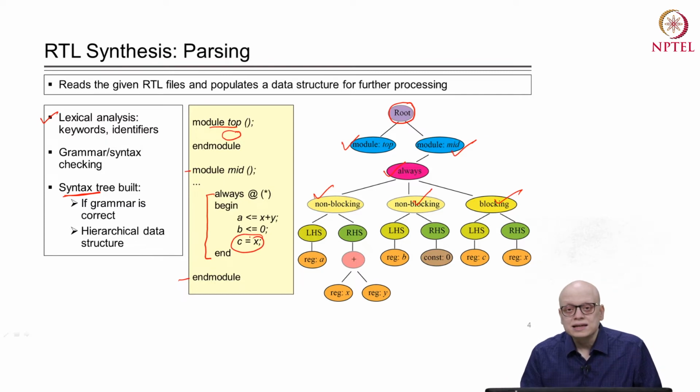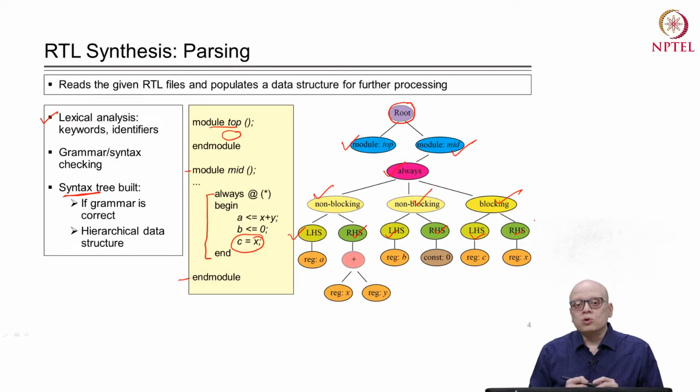Each statement has an LHS and an RHS, so a non-blocking statement will contain an LHS part and an RHS part, and so on. This is how the given Verilog code is parsed and a hierarchical data structure is built. Once this hierarchical data structure or parse tree is built, the RTL synthesis tool goes to the next step.